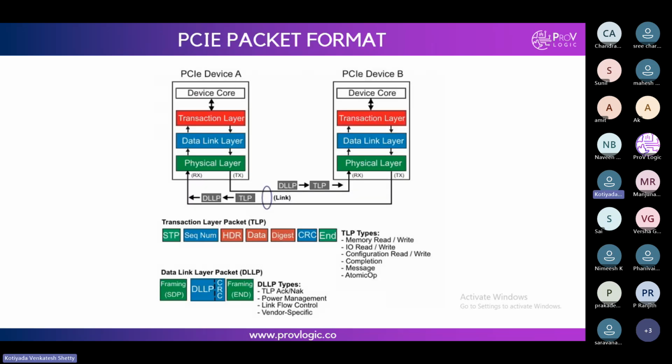If you have any notes, please write them down. Today I will explain the packet flow, and how the initialization will happen in PCI. These are the two important things. If you want to learn PCI, these are the two important things everyone will ask in interviews. If you want to debug anything, you need this flow. First of all, we will concentrate on the packet flow.